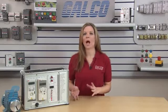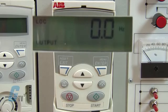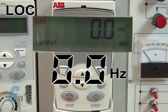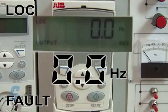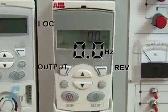After verifying that the wiring is correct, I can apply power to the drive to begin programming. This particular drive has a basic control panel mounted to the front as opposed to the advanced control panel. The basic control panel has a single LCD line display and is divided into 5 areas. The upper left indicates the control location with either local or remote. The center shows the value or parameter with the unit of this value displayed in the upper right. The lower left corner shows the panel operation state. This could display output mode, parameter mode, main menu, or fault. Finally, the bottom right indicates the direction and status of the motor.